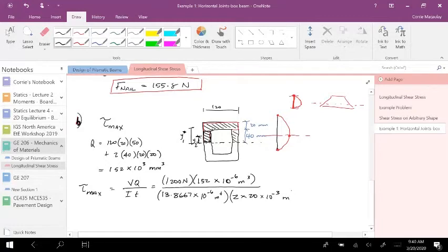Do you mind explaining that real quick? All right, so here's the thickness. There's nothing here, right? It's an open beam. So the thickness that I need to worry about is this distance and this distance. Okay, got it. That's basically what the beam is going to try to pull apart, because we've got the maximum shear stress. If I put that beam in bending to failure, it's probably going to break right along the length of that beam, right at the neutral axis.